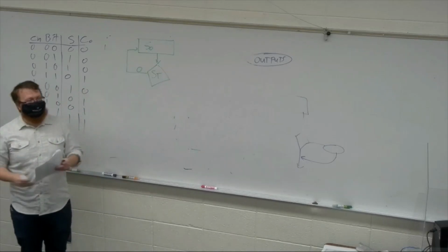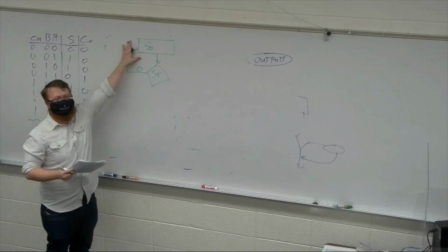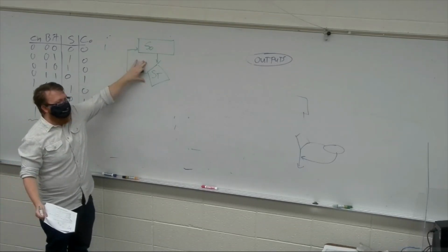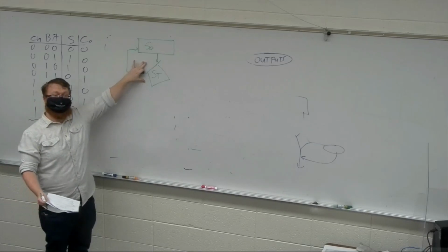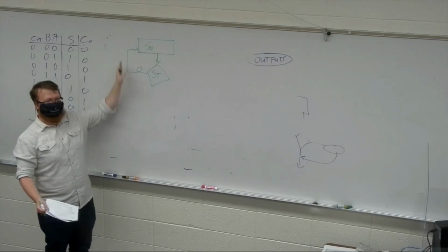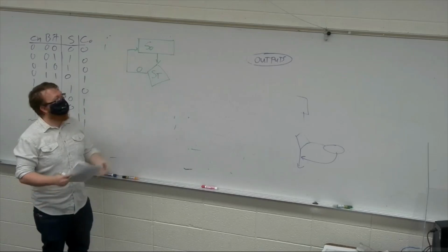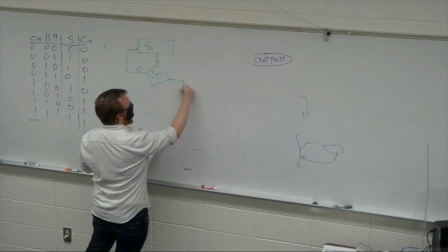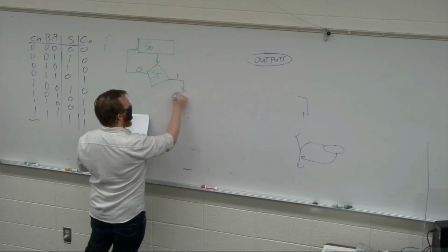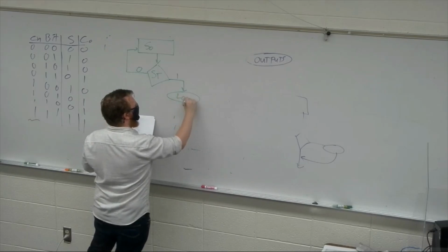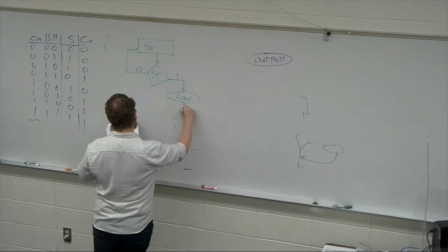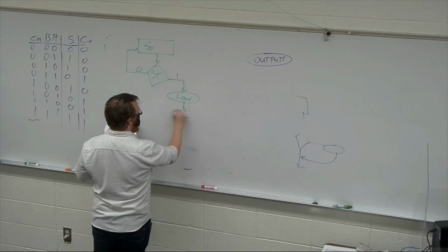So in this control logic, I come into the state, right? System turns on, I enter state 0. And the first thing that I'm doing is, should I start? If the answer is no, let's just hang out and do nothing, right? The next decision is, if I should start, then I want to send out a load signal. And then we're going to enter a new state.